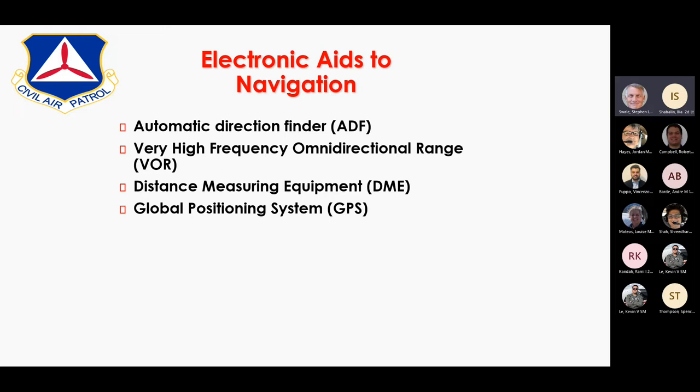Six-pack airplanes will have dedicated displays for individual electronic nav aids. So again, if you've got that turned on, then you should have it tuned and adjusted so that it's giving you real information rather than just a needle floating around to distract you or make you think that you know something that you really don't.